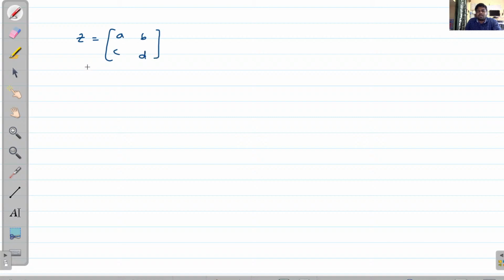Now for the same network you need to evaluate the Y parameters. So in that context, what you have to do: Y equals Z inverse. Already you have the Z parameters, now you can evaluate Z inverse. So this is in matrix form. So how do you find the inverse matrix for this 2 cross 2?